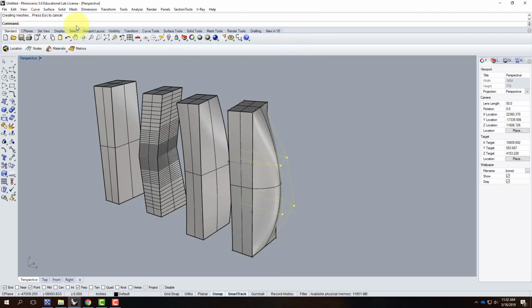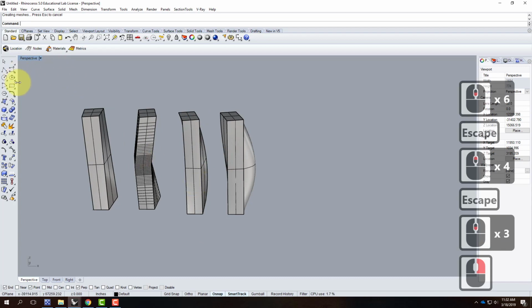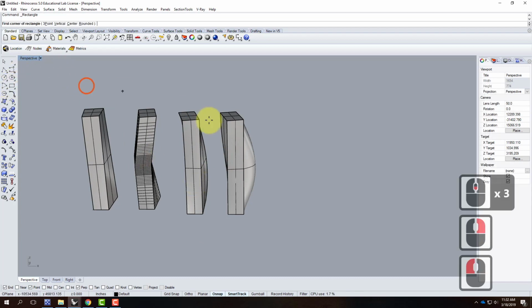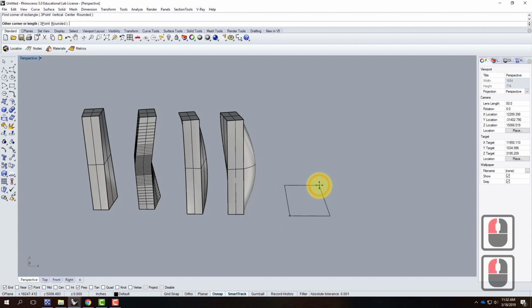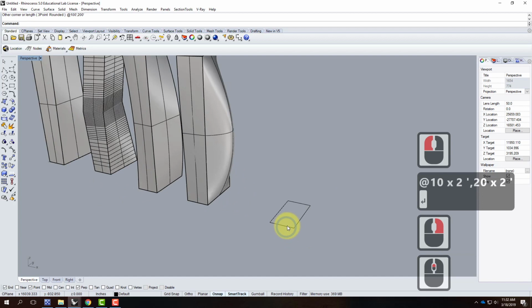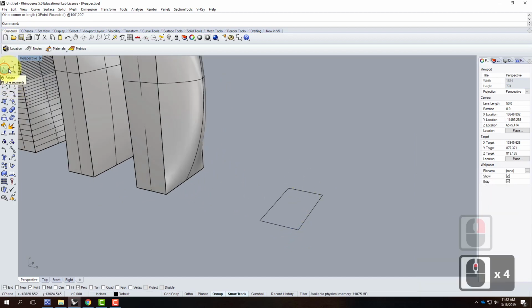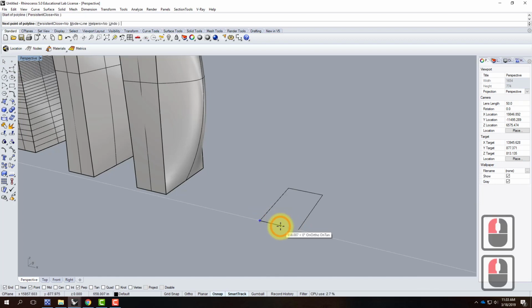So if you stick in the cage edits to a degree of 2, it should keep you in a developable surface. Sometimes, in some weird cases, it gets off. But for the most part, you should be OK. So you don't have to feel like you're stuck with just the rectangle shape. You can, of course, change what's happening down at the base. So instead of having a 100 feet by 200 feet rectangle there, maybe I would work within this and shave off a corner. So I might go in to my polyline tool, and I might say, OK, I'll start here,